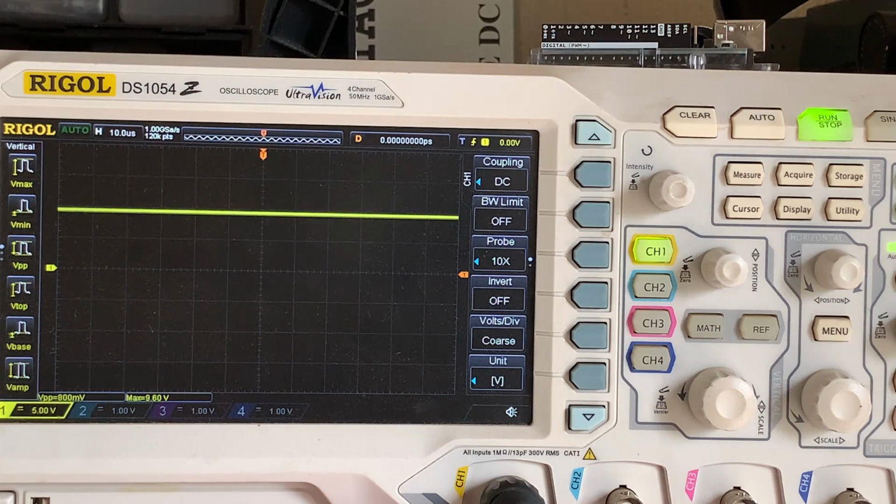Zener diodes are notorious for it, and so are resistors. So as the temperature goes up, this thing will go out of whack. So I would use the differential type amplifier that we've used in the second circuit, and then you know you're a bit more stable. So let's finish up.